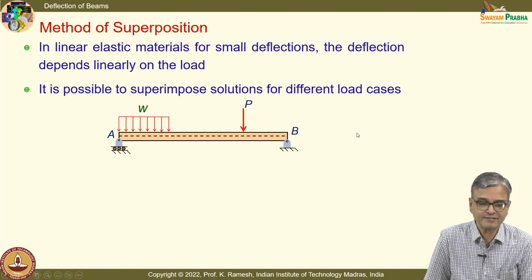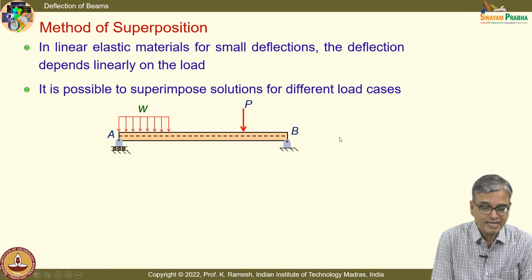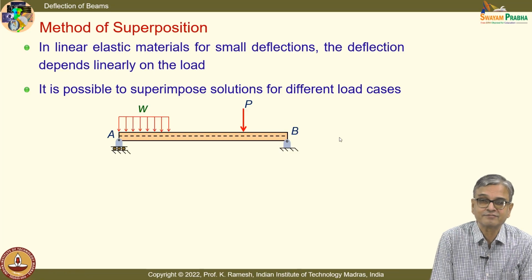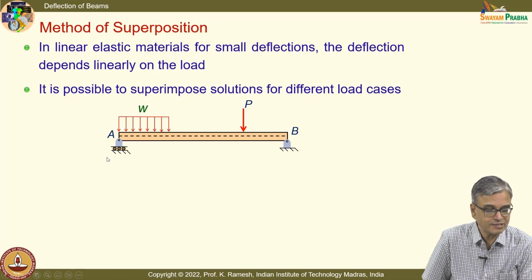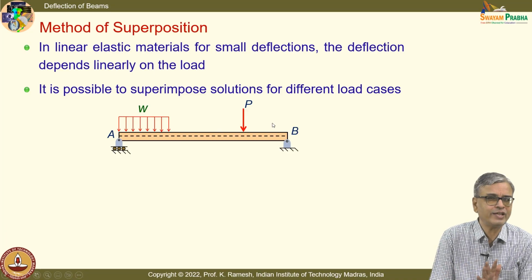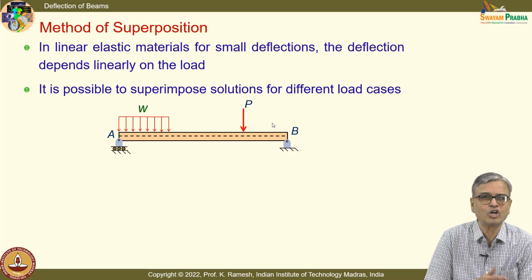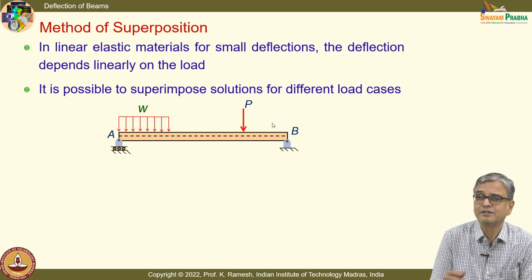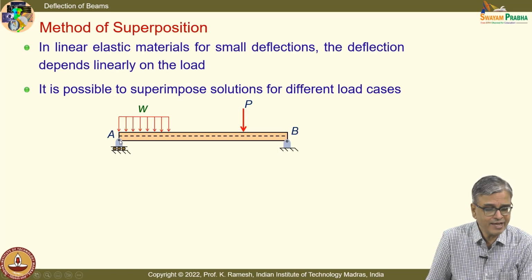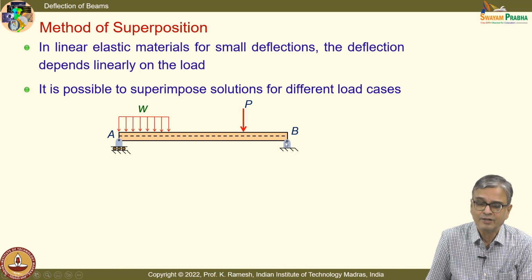Okay, I have a load case. Can you draw the anticipated deflection curve? Because I have the support, this is the roller support, this is the pin joint. I have unsymmetric loadings, the loading is not symmetric. Have a training, you make a mistake, no problem, you draw the deflected curve. So, you also learn, because I can have any slope here, this also permits any slope, but the deflection is 0 at these 2 points, that is what I know.